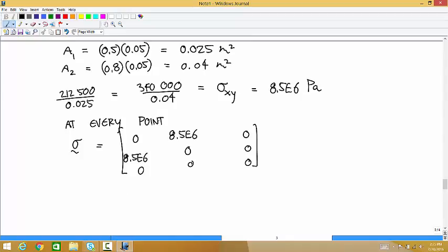Well, it is because I made the numbers so that it worked that way. But if they weren't equal, remember, it has to do with the rules of stress tensors. This set of problems is all about members that obey the rules of stress tensors. A stress tensor has to have a shear traction going this way that's equal to the shear traction going this way. That's one of the rules of the stress tensor. And so if that wasn't the case, this wouldn't fit into that category.